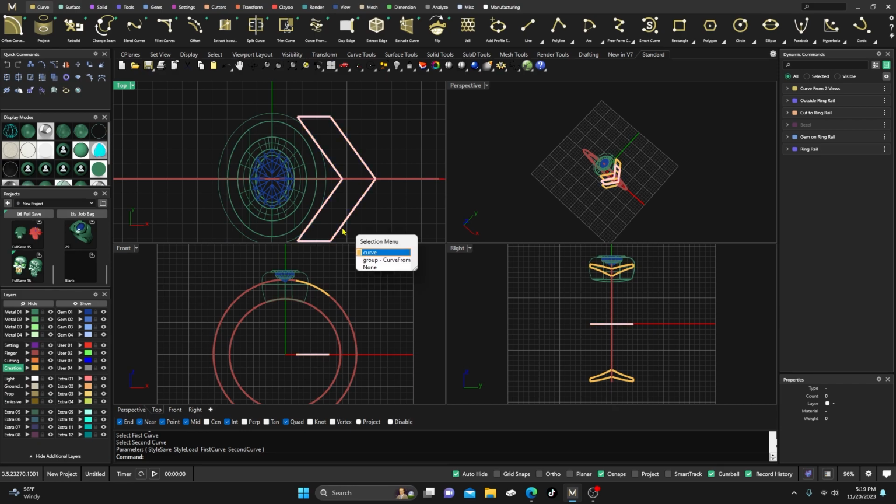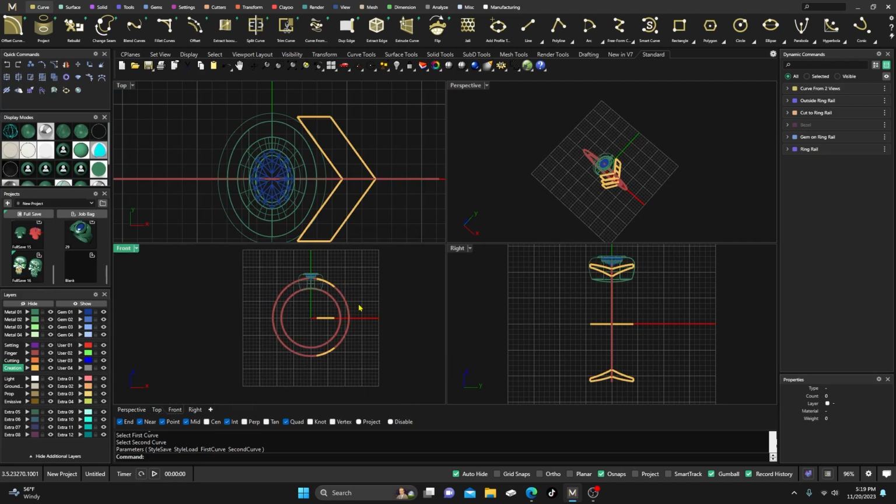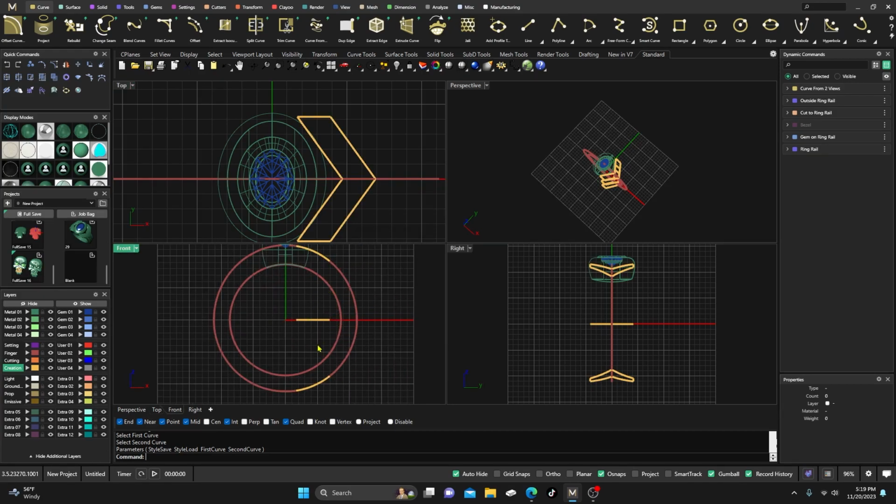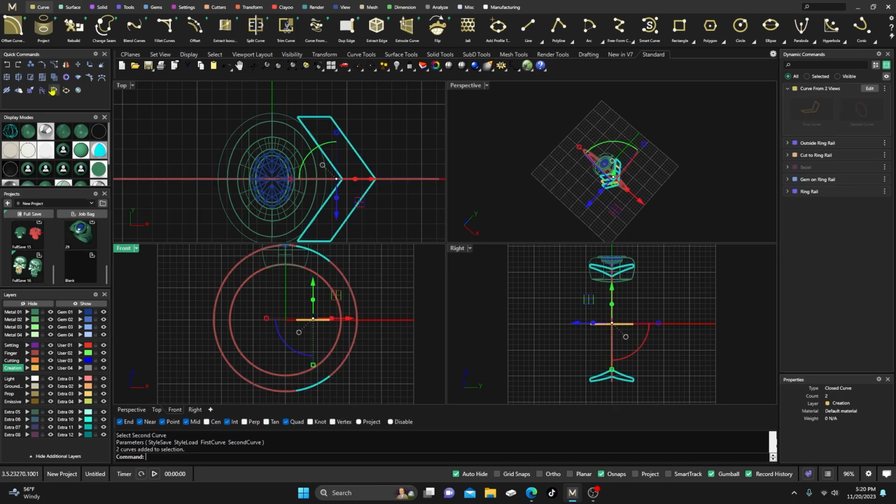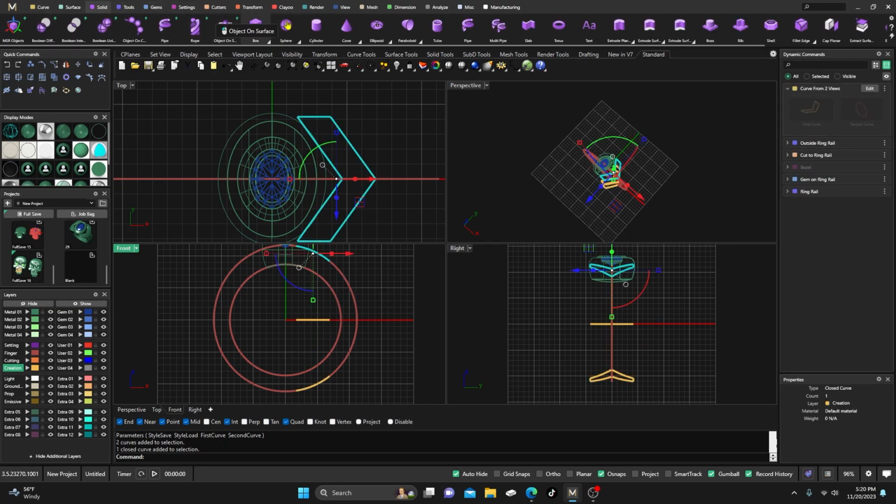Now this, okay, that's the bottom one. This is the group. That means it's top and bottom, right? So we want to go ahead, you can shift control, select the one. I'm just going to go ahead and ungroup them, make it easier if I can select it, ungroup it. Okay, now I'm going to take this curve up here and I'm going to go to solids and I'm going to go to extrude